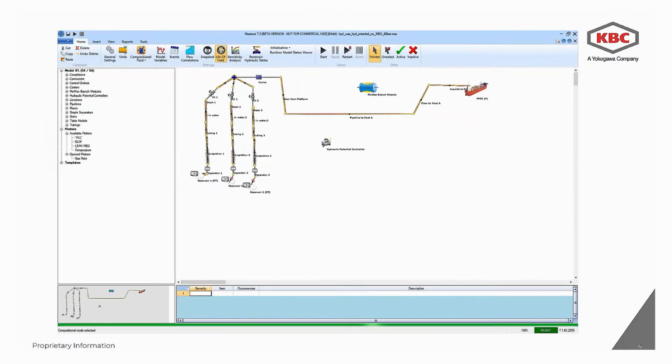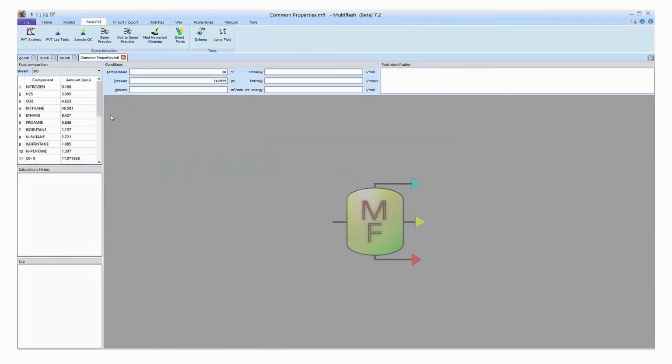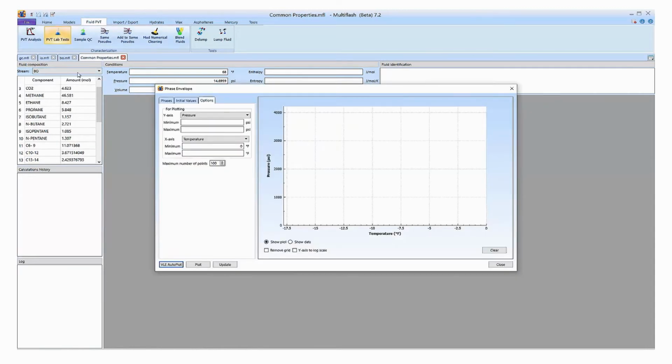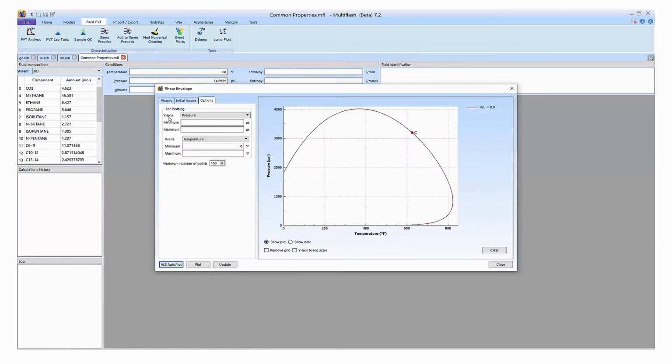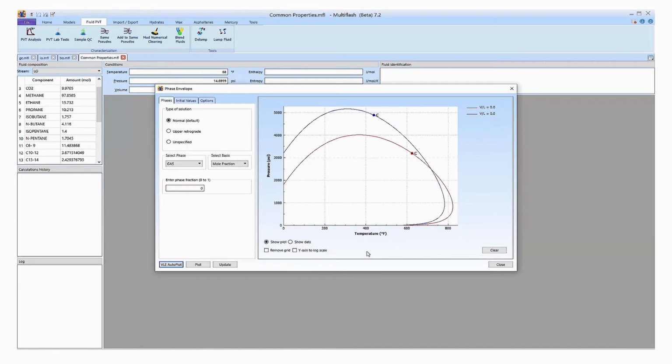Fluid characterisation may be done several times at different stages of a project. The characterisation with a common set of petroleum fractions is very useful to limit the number of components. This is important when modelling large fluid sets commingling in transport or processing. However, simultaneous characterisation of all the fluids sometimes is impractical. For instance, when a new well or reservoir is brought into production at a later stage, the recharacterisation of the whole set of fluids may be necessary to keep consistency.